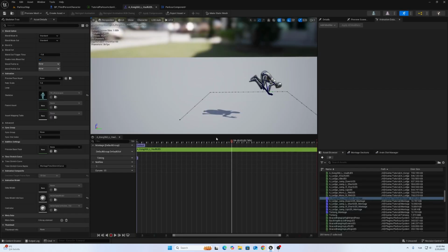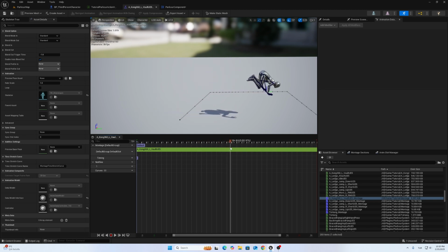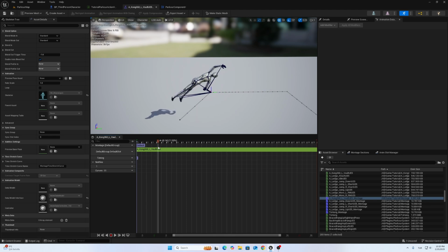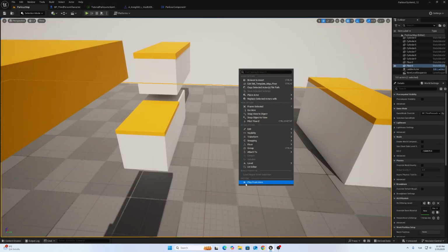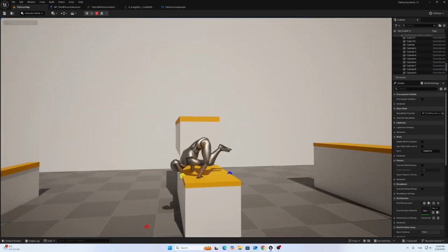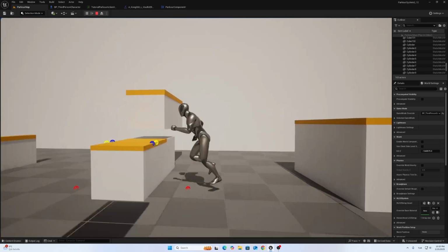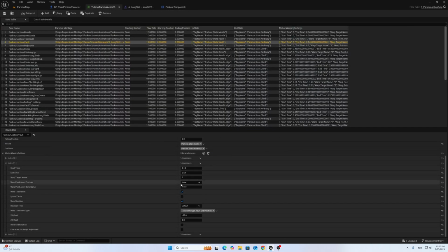I want to decide the warp time coming from there and here, and okay. Position is 0.63, which is great, and you can see that the Z offset is not great because our character's hand is shrinking, so we can raise the Z offset a little bit.